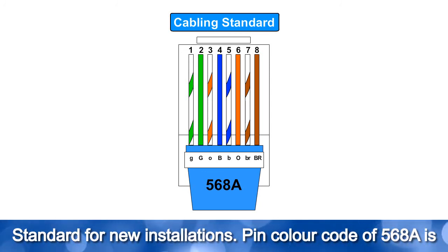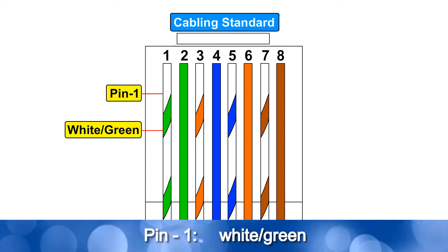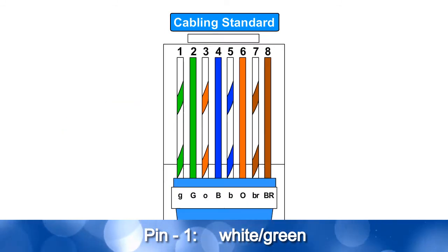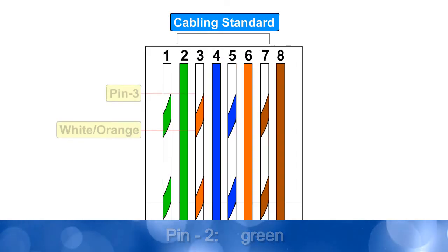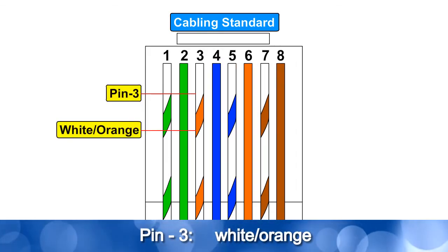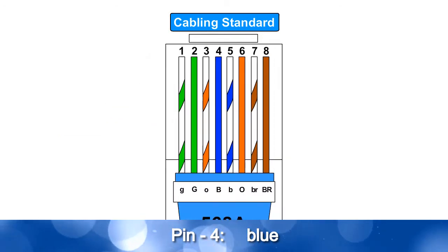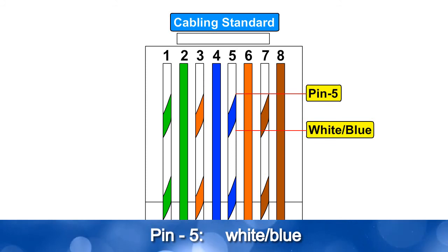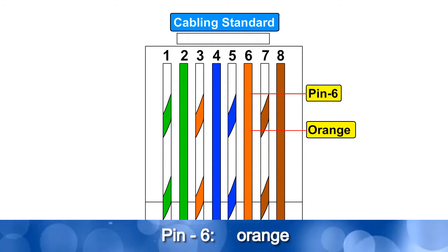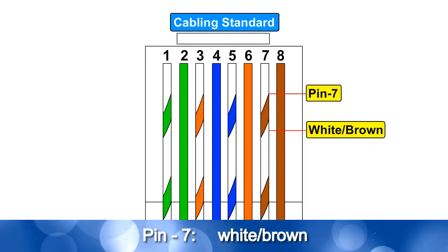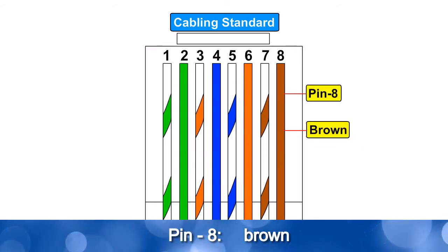Pin color code of 568A is: pin 1 white green, pin 2 green, pin 3 white orange, pin 4 blue, pin 5 white blue, pin 6 orange, pin 7 white brown, pin 8 brown.